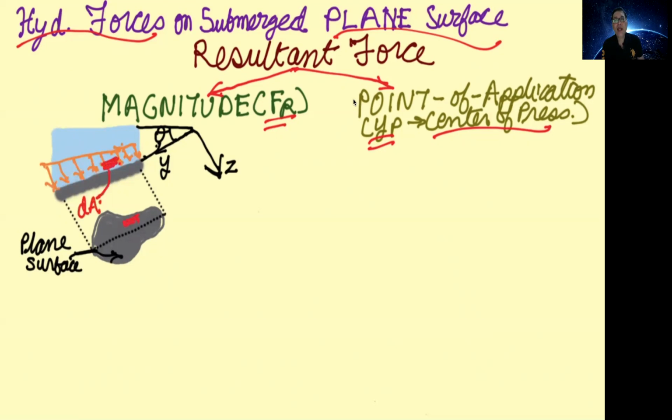Now this represents a parallel force system, and in a parallel force system we have to calculate a resultant force. To calculate the resultant force, basically we will integrate this pressure distribution. All of you know this, that we will do an integral of the local pressure distribution, so we'll start with an elemental area as shown here, and we'll apply the integral of P dA. So in this small area, there is a pressure which is acting.